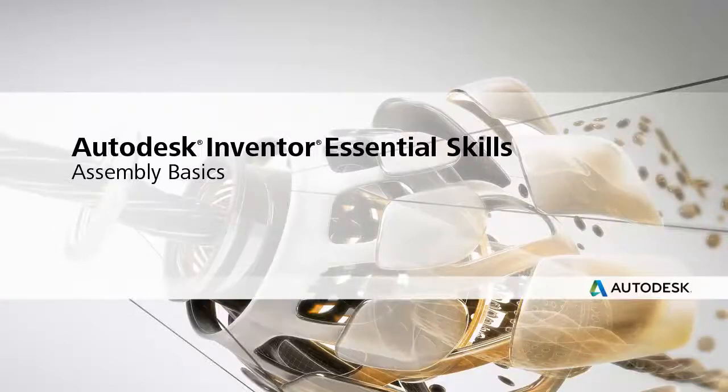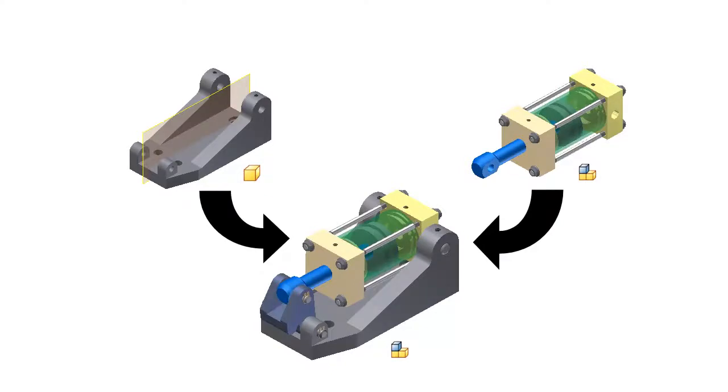This video introduces assembly basics. Create an assembly to position components, define movement, check for interference, and create a bill of materials. Assembly files contain references to part files and other assemblies.